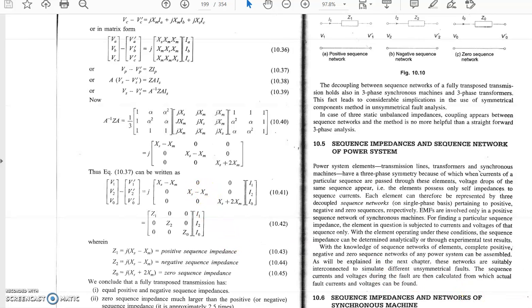So the conclusion is that if we provide a positive sequence supply, positive sequence meaning whatever we studied up to now in machines or other power system components, that is A, B, C with a phase difference of 120 degrees, if we provide such a supply to the transmission line, the impedance offered by the transmission line is xs minus xm.